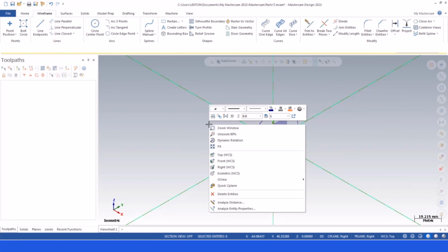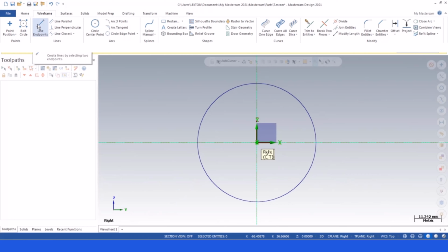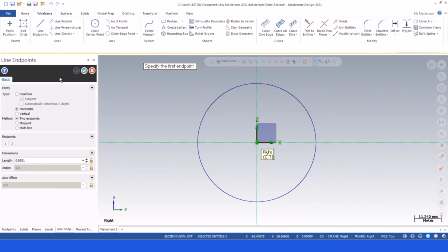After that, we can also use the right mouse button to select right view. After that, we can turn to line and point options. We can click horizontal line, click here and here. After that, we can write our axis offset here. According to my VCS, this is my Z distance according to the XY plane here. And then we can write here 15 or maybe 20 better.